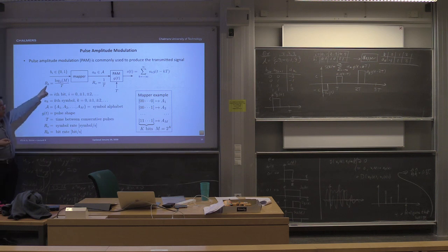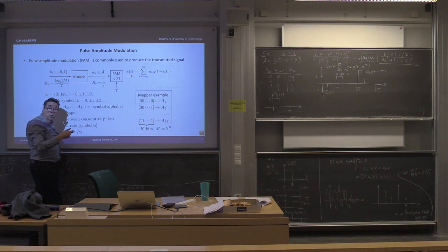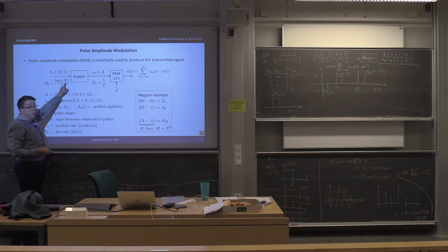We care about this. So give me 2 ways to get higher data rate. Suggestion for something. What could be changed in the design to get high bit rate? Faster sampling and also more bits per symbol. Oh yeah, both of them. So we can reduce T, so transmit pulses quicker, and we can increase M to transmit more bits per pulse. So these are the 2 things.